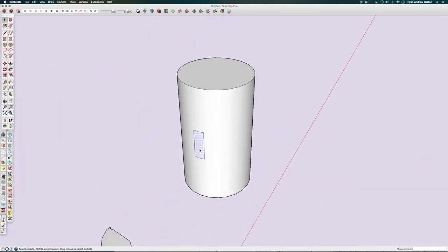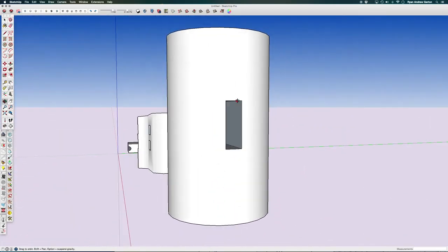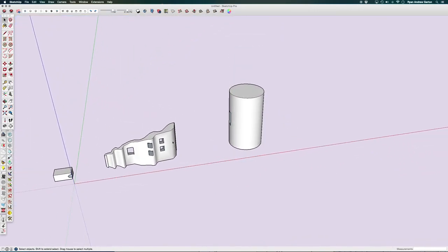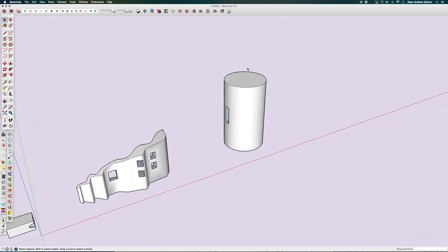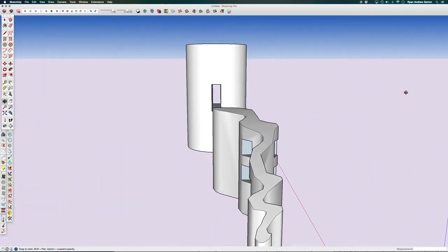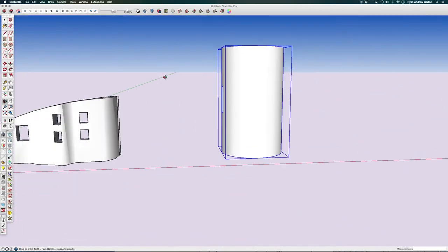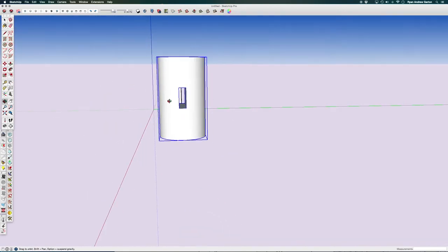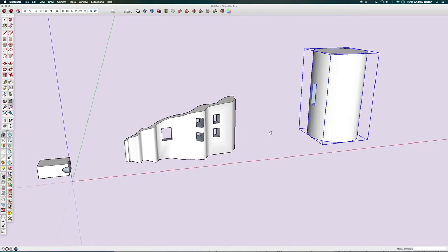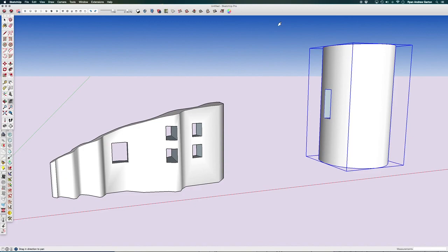So in essence, ultimately, you can pretty much make anything in 3D using just this tool and push-pull, because push-pull will give you your solid. That brings this up into place. But now that I know that I can carve and start cutting these things apart, the options are pretty open-ended. So we'll be using this in the videos to come, going back to that interior model to start cutting apart some of that stuff that we thought at one point was not cut apartable.